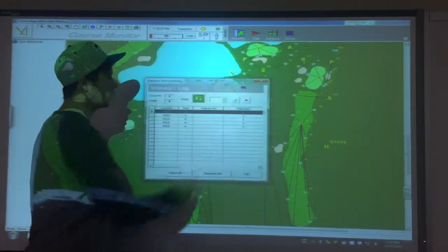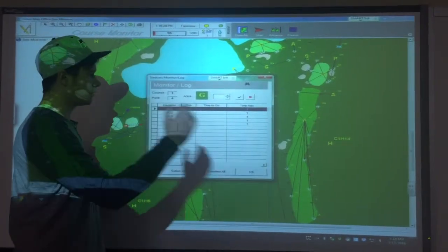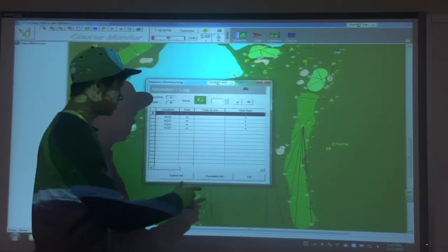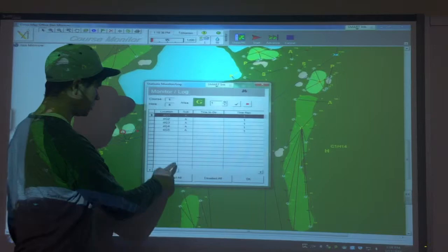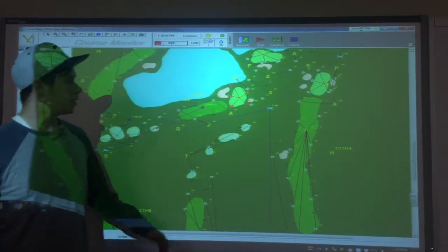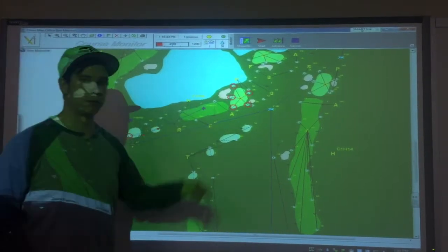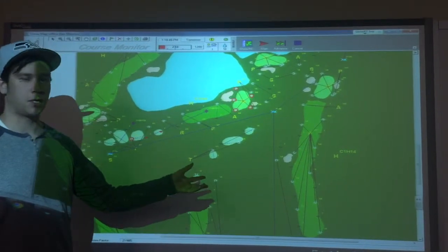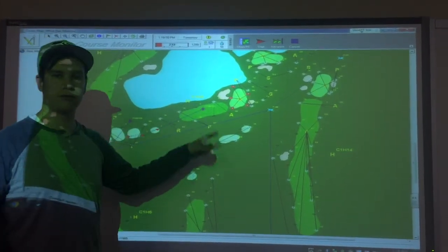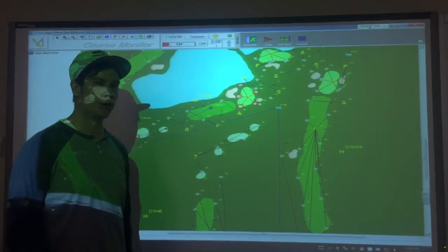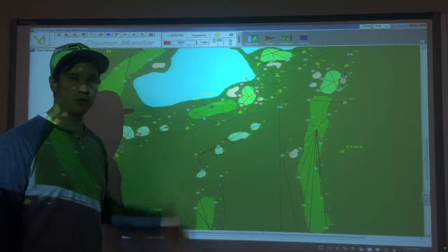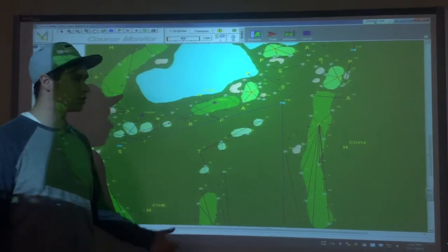Now, if we try starting the green, that's on a different outflow pipe than the tees. We'll go up to 1 minute. We'll select all. We'll start it and hit OK. As you can see, that's a loop system. So it's 90 gallons per minute on both sides, and so because of that, it can handle all of the sprinkler heads in the one system. It combines to create 180 gallons per minute allowance in that system. So that's how you turn on the stations, and that's how you run the station.